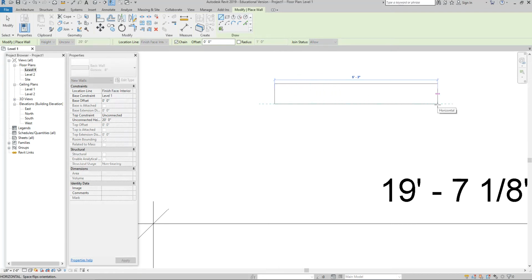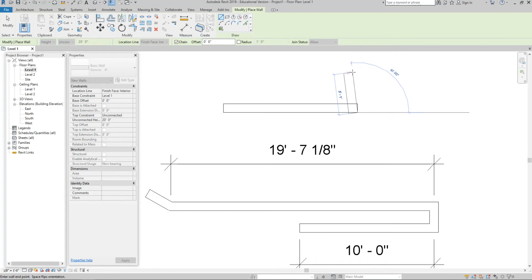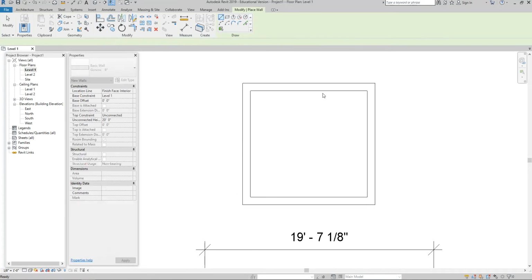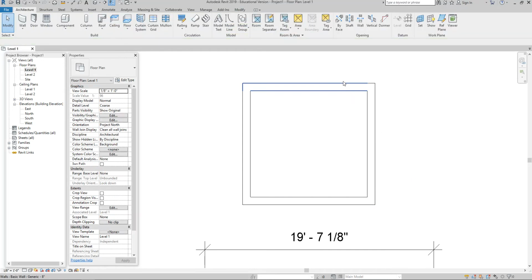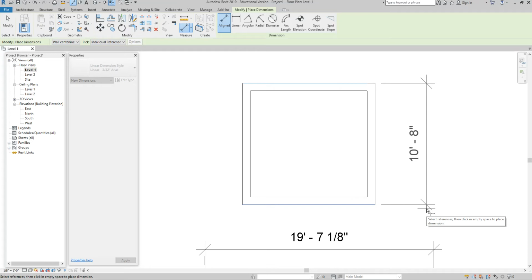You're going along drawing, okay, 10 foot, enter, right? And I come up here, 10 foot, enter, and I come over here and I type 10 foot, enter, and then I close it up. That's all well and fine, right? Except that it's really not 10 feet, right? That building that you drew with a location line to the exterior is actually 10 foot 8, right?